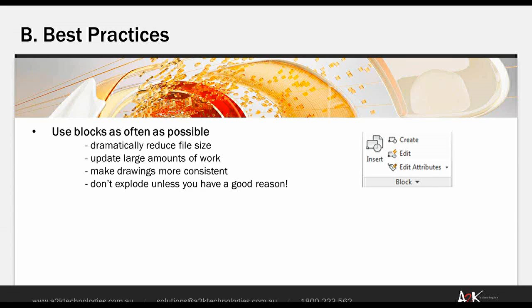And the final one is really important as well. Don't explode them unless you have a really good reason. Obviously, once you've exploded them, they're not linked back to the original block definition. So when it comes time to update, you'll find it very hard. You have to go through and update each one individually.